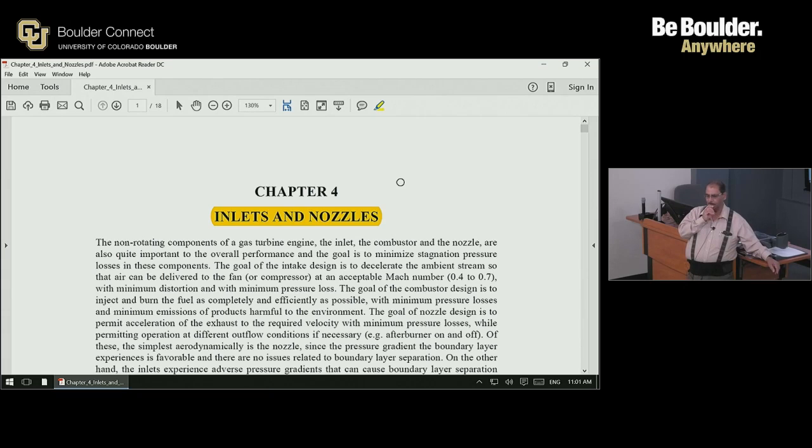A long time ago they discovered that instead of having a single mount, they had to have a sort of Y mount to prevent that distortion of the casing. Now, that suggests that maybe the way they attach the engine to the aircraft may be a problem, because this didn't show up with the Bombardier engines, C-series aircraft engines, but shows up with A320.